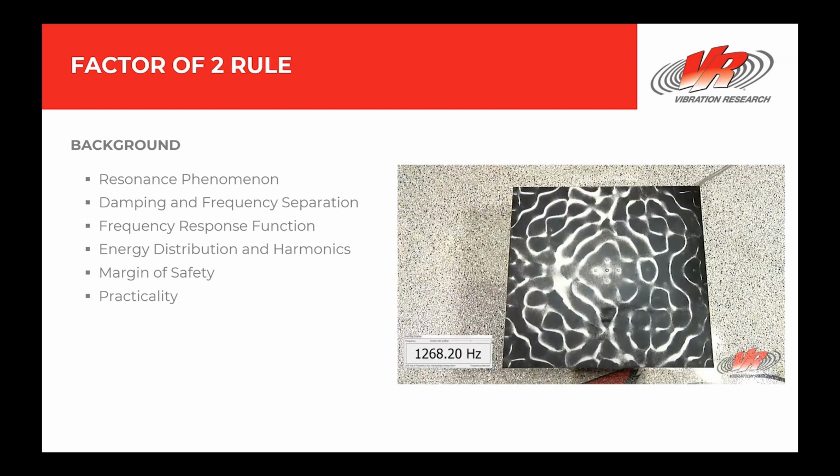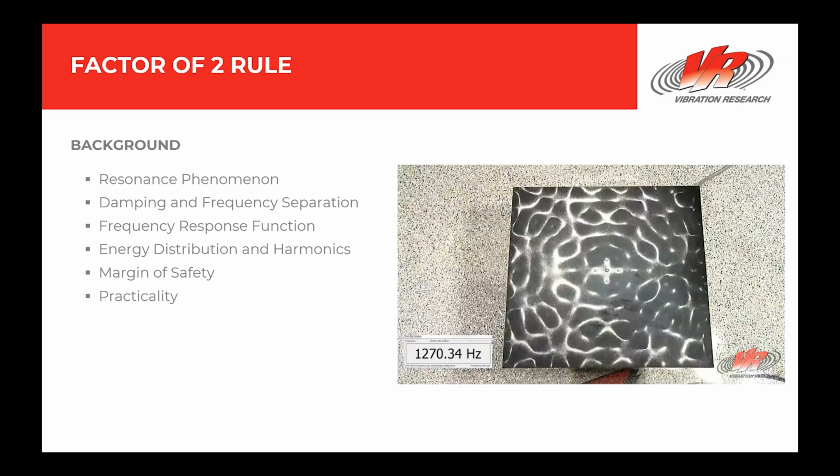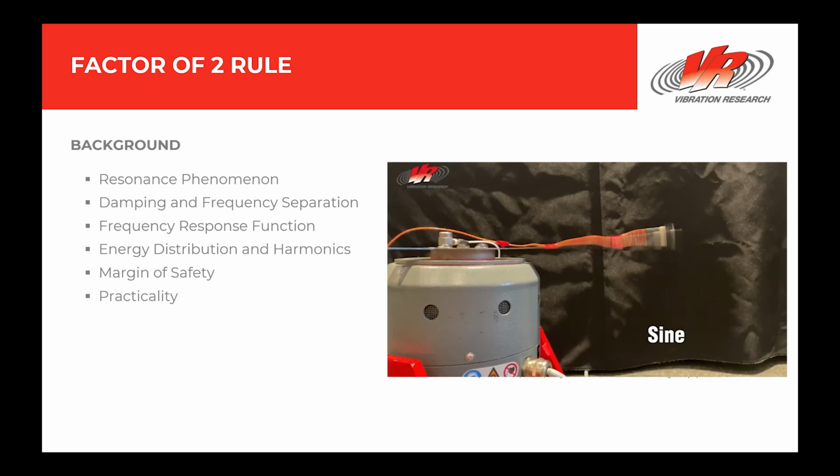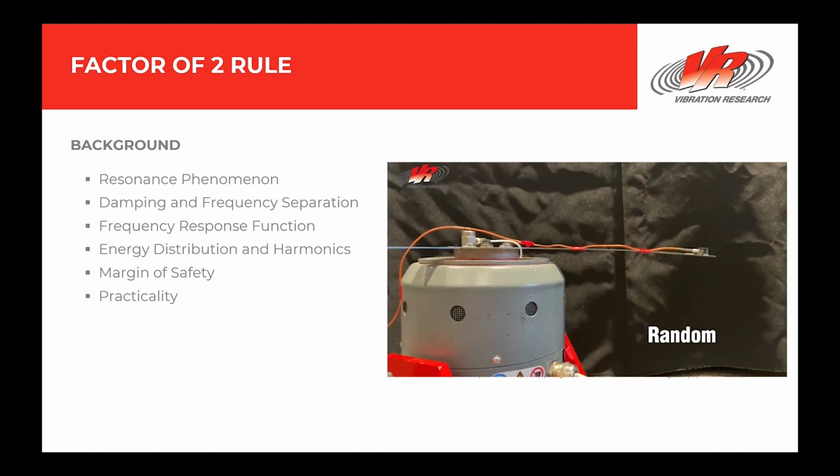Each mode is associated with a particular natural frequency, and the shapes of these patterns are called mode shapes. For example, in a beam, the first mode might be a simple bending shape, second mode a double bend shape, and so on. Each mode shape corresponds to a higher natural frequency as the mode number increases.